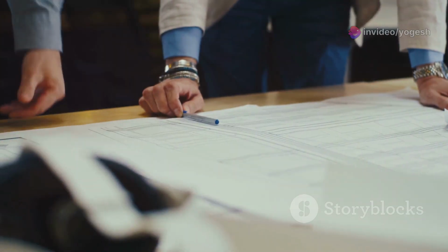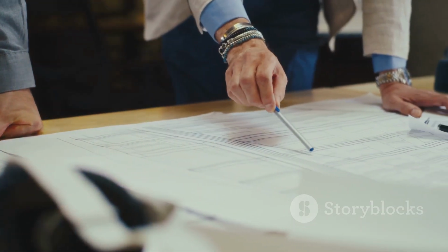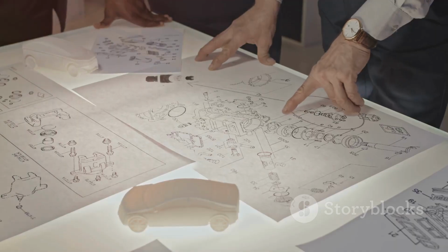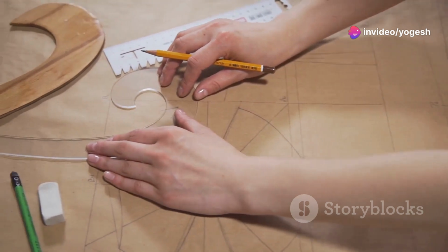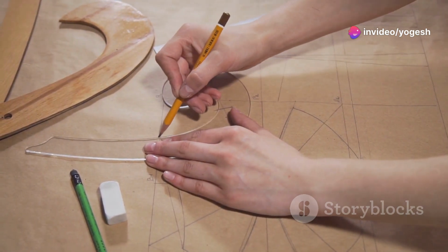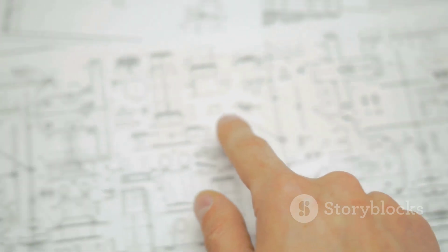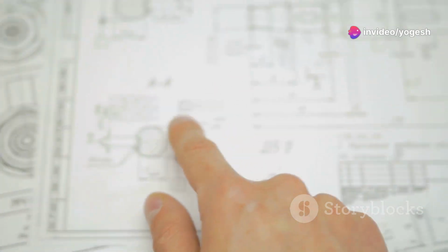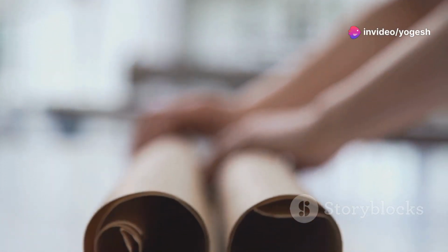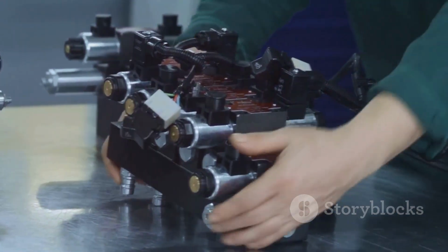Tip number 2 is all about harnessing the power of GD&T, geometric dimensioning and tolerancing. Think of GD&T as the language of functional engineering. It goes beyond basic dimensions to control the form, orientation and location of features with laser precision. Instead of simply stating a dimension with a plus-minus tolerance, GD&T uses symbols and datums to define acceptable deviations clearly. GD&T might seem intimidating at first, but trust me, it's your best friend when it comes to creating unambiguous drawings. It ensures that your parts will function as intended and fit together perfectly, even with manufacturing variations.